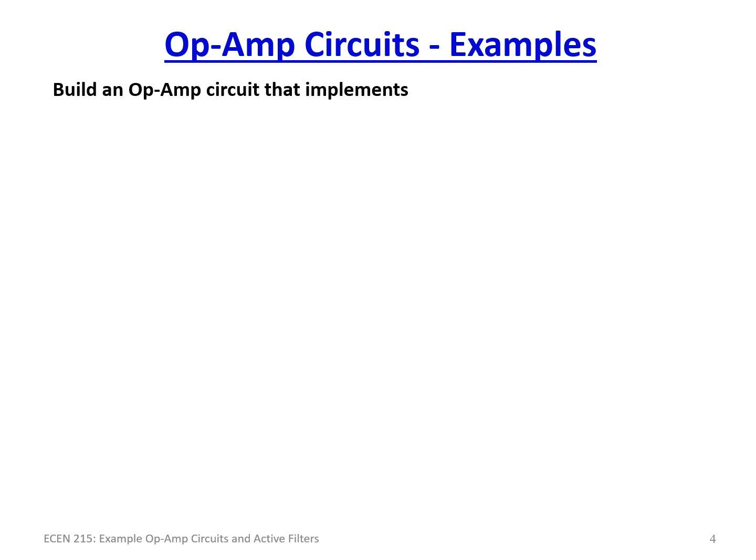For this circuit, what we need to implement is simply 10 d/dt of V1. So if we go back and look at the different circuits we had in the previous topic, we actually have everything we need. We have a differentiator and we also have an inverting amplifier, because the result of the differentiator was minus 1 over RC d/dt of its input voltage, which is an inverting version. And since we don't want to invert, instead we want a positive gain, we're going to need to put in an inverting amplifier. We can put it either on the input or on the output. You can swap the stages. You can have stage 2 be the differentiator and stage 1 be the inverting amplifier, or vice versa.